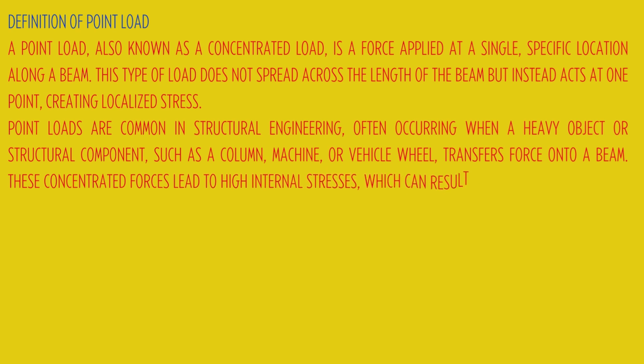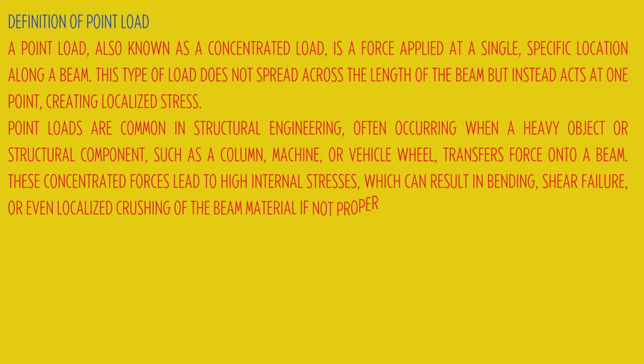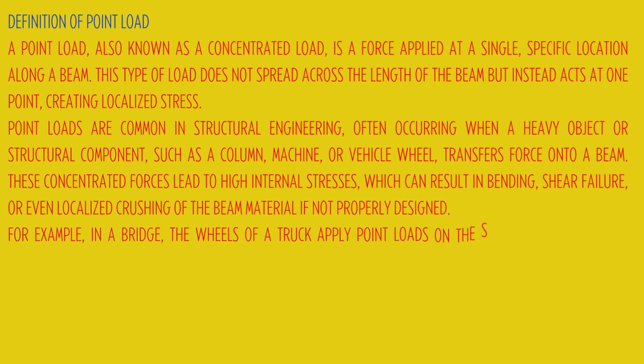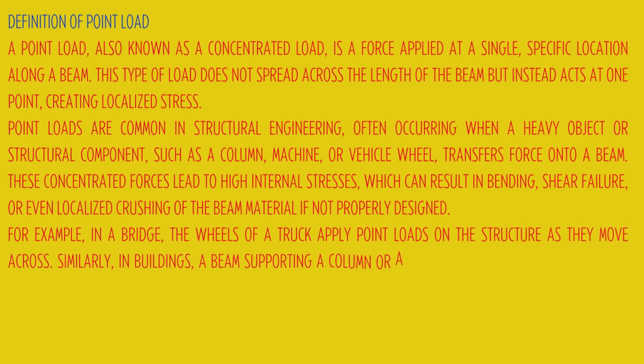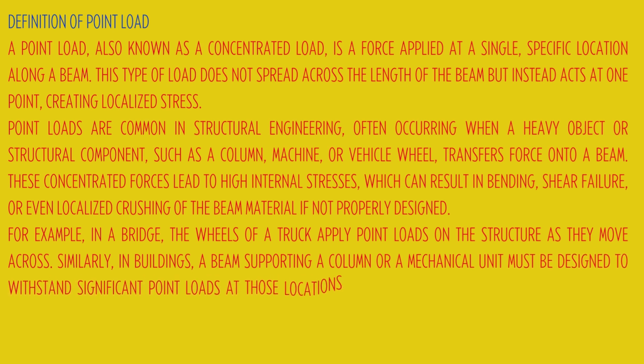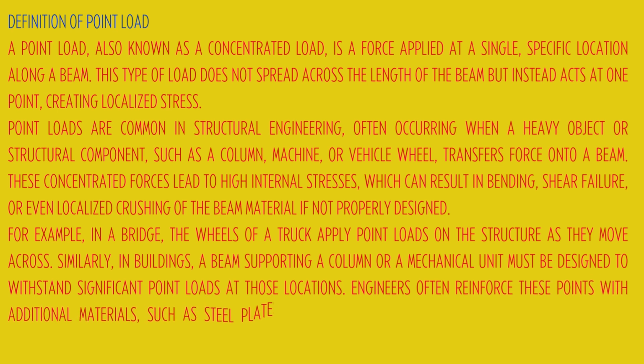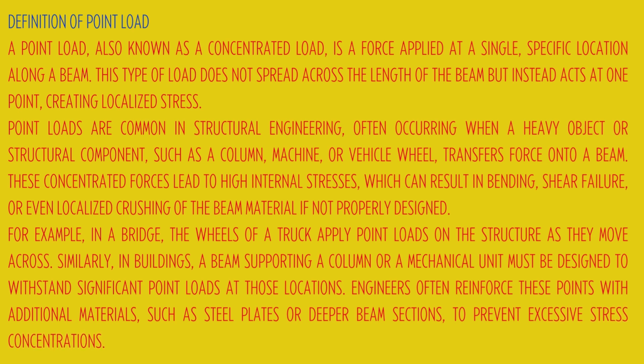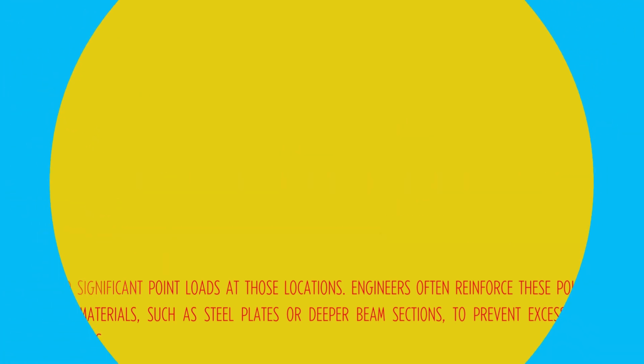These concentrated forces lead to high internal stresses, which can result in bending, shear failure, or even localized crushing of the beam material if not properly designed. For example, in a bridge, the wheels of a truck apply point loads on the structure as they move across. Similarly, in buildings, a beam supporting a column or a mechanical unit must be designed to withstand significant point loads at those locations. Engineers often reinforce these points with additional materials, such as steel plates or deeper beam sections, to prevent excessive stress concentrations.